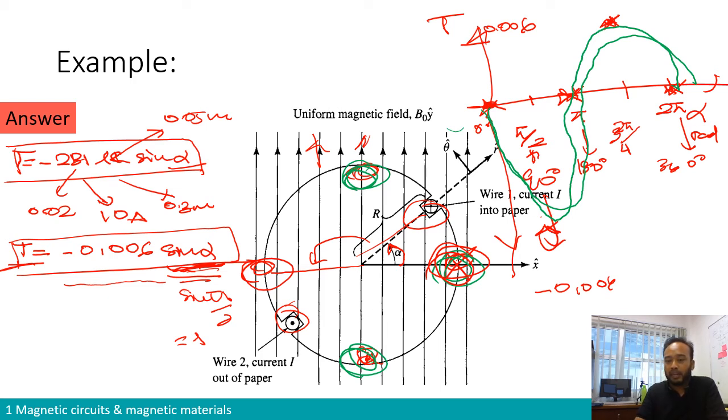Why? Because we know that the forces are either in this direction or in this direction. If you are situated at 0 degrees or 180 degrees, all the forces are on the x-axis and pulling outwards, which just creates a force that contracts the rotor, but it doesn't produce any torque. In order to produce torque, the maximum is when it is over here, right? And in between, you'll be creating a force that is in the middle between 0 and either the maximum or minimum.